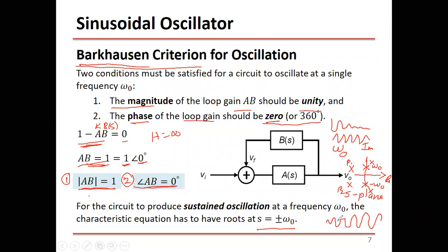It will not grow to infinity, right? And as you said, it's unstable, and we need the circuit to be unstable because oscillation means unstable. We are designing the circuit to be unstable, but the perfect design is to have omega 0 exactly on the imaginary axis, which is impossible, by the way, because you cannot keep the poles there. You might design the circuit with resistors and capacitors to locate omega 0 on the imaginary axis.